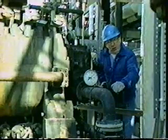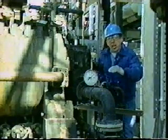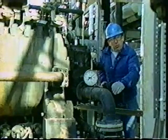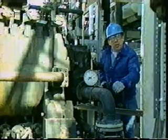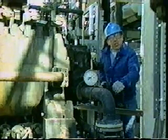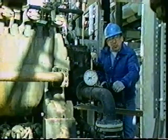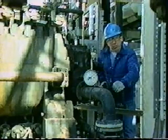A thrust bearing failure can be caused by thrust reversals that occur from the rapid and violent recirculation of the gas. Sometimes these thrust reversals are so violent they can exceed the load capability of the thrust bearing, causing it to fail. This combination of thrust bearing failure and overheating can be catastrophic to the centrifugal compressor.